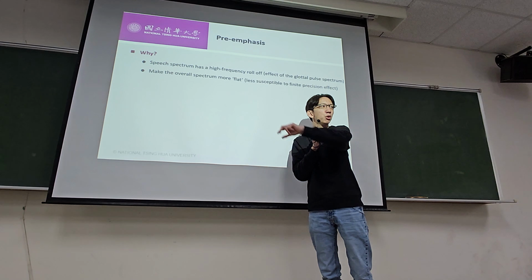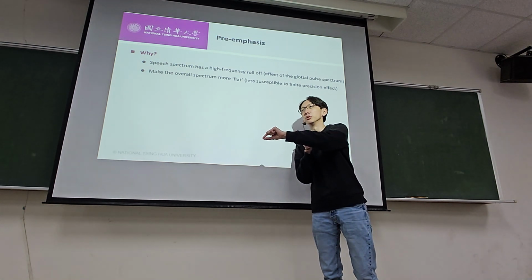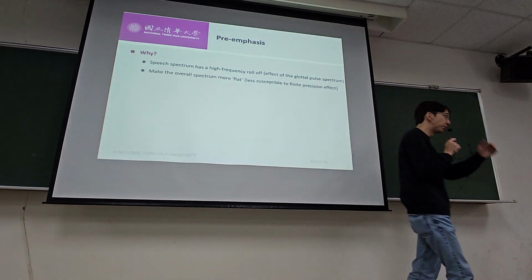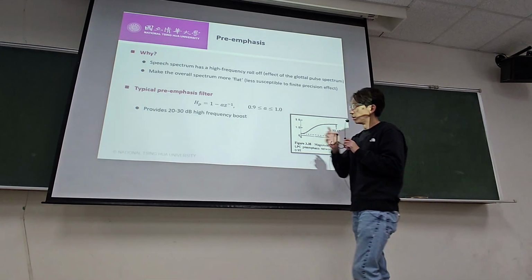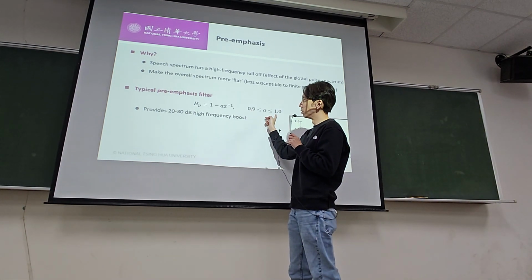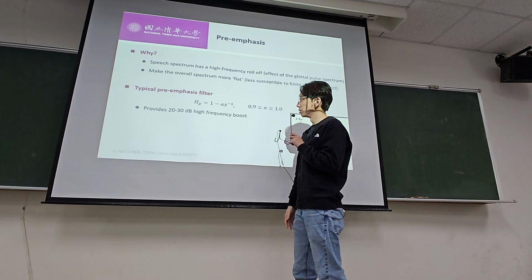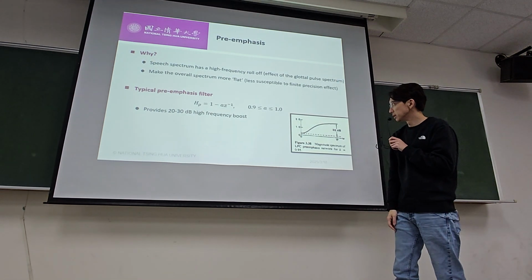Okay, all this multiplication, you may make that value way too small. So you want to do a pre-emphasis. Pre-emphasis is very simple. It's just some a between 0.9 to 1. The filter is 1 plus a z to the minus 1.